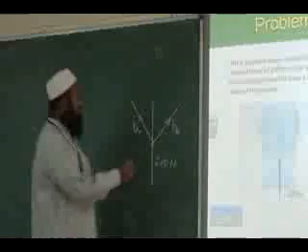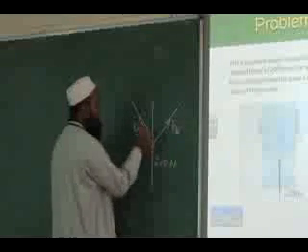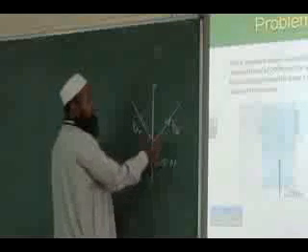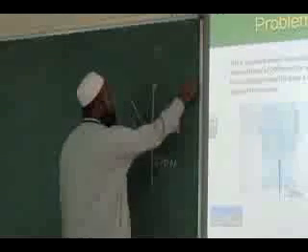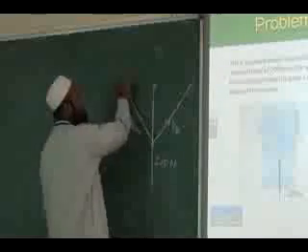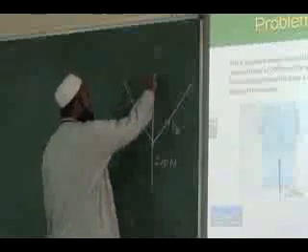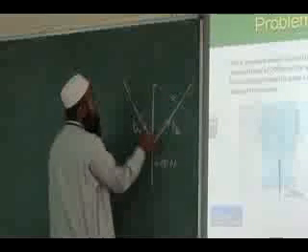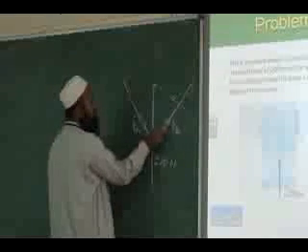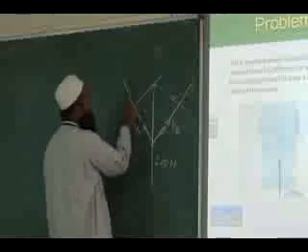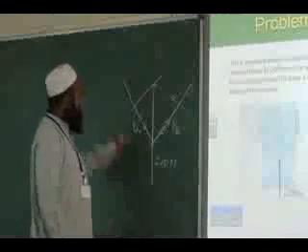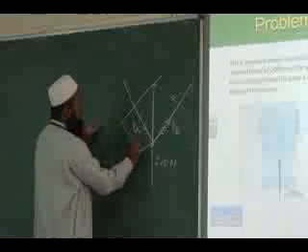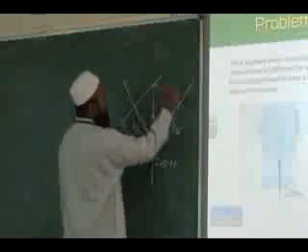If you follow the graphical approach, we can draw a 200 Newton line to some scale. Then you know the lines of action of A and B. So from the head, we draw a line parallel to this and also parallel to the other vector. We get the parallelogram. So now we get the magnitudes of forces FA and FB.